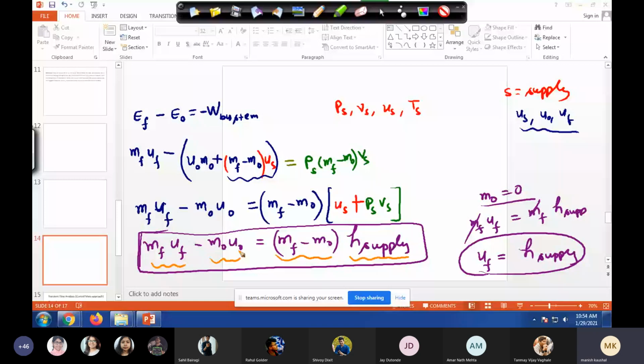But the moment you take a finite pressure difference, you cannot apply the work done formula, because that work done is defined for quasi-static work. But if you go into the depth, you find that the work done is happening at the boundary of the system, that control mass. So inside and outside pressure are almost equal. So you have to only take the P supply.